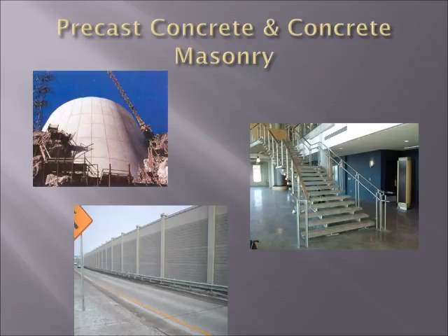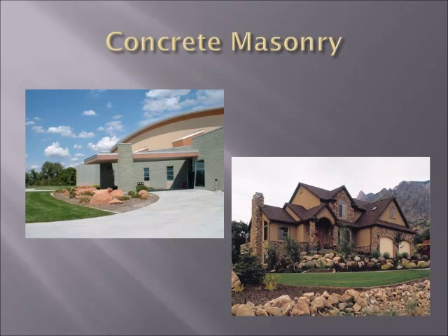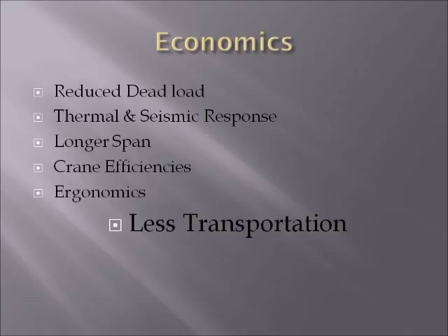The economy found in precast concrete and concrete masonry through the use of structural lightweight concrete may be very similar to those found in prestressed concrete. Transportation, erection, and installation costs are all areas that may benefit from the use of structural lightweight concrete. In some designs, thermal and acoustical properties, as well as concrete durability, may show some economy, especially if looked at through life cycle costing.